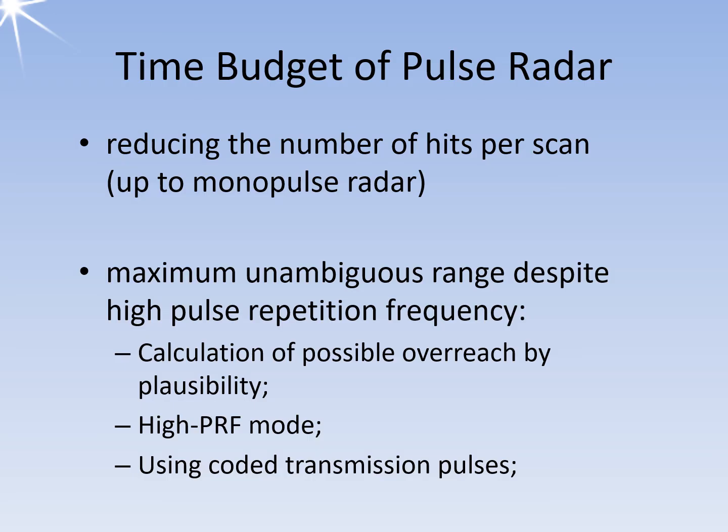With the digital shaping of virtual antenna patterns, various virtual directional patterns can be generated in memory, which then determine the direction of reception of various echo signals. The use of respective coded transmit pulses makes runtime and distance measurable.